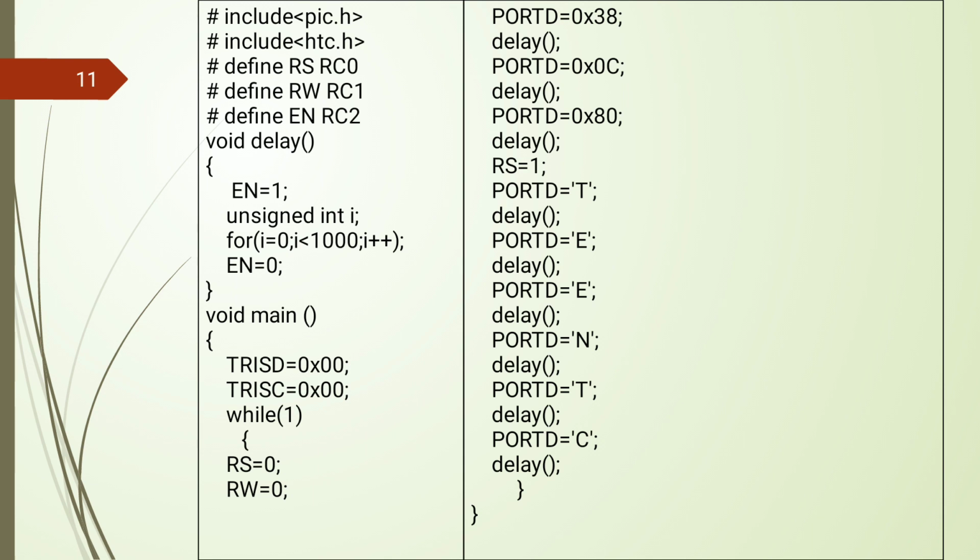So we move further to the main function. Here in main we need to specify the given ports as output ports. Here there is no need to specify any input port or input connections. In the next part, that is for interfacing of LCD along with the keypad, or LCD along with keypad with 7 segment, in that case input as well as output conditions are both required. Here we are only interfacing LCD as a display device or output device, so no need to specify an input port, only an output port is sufficient.